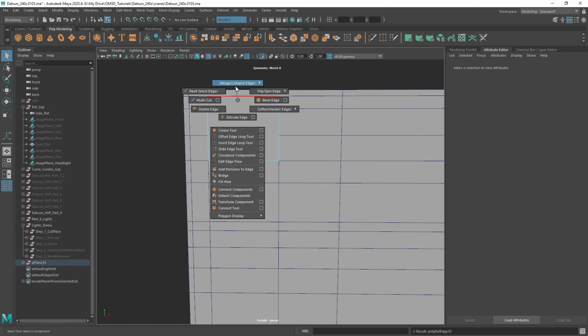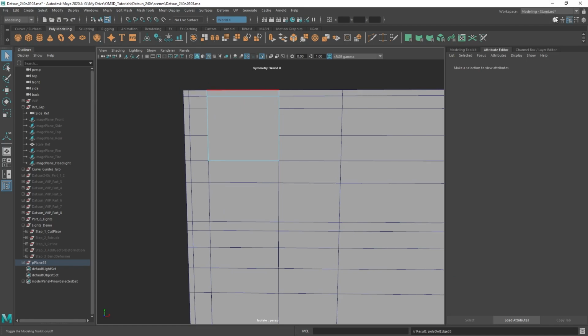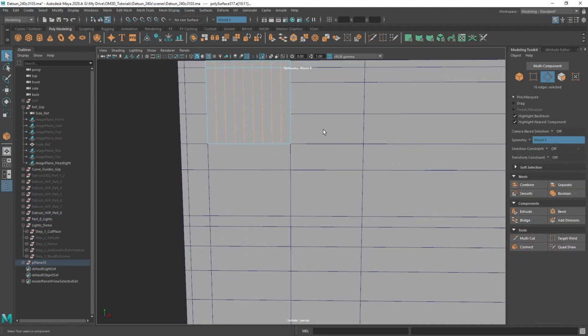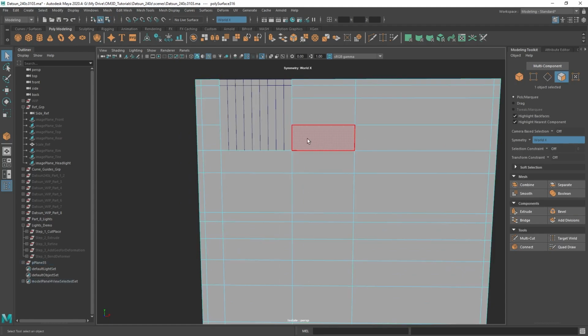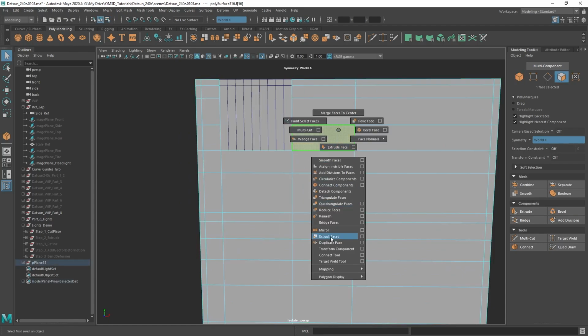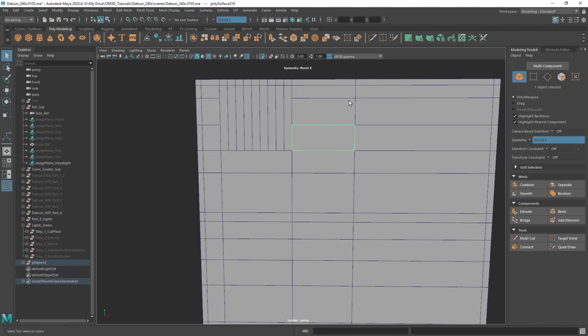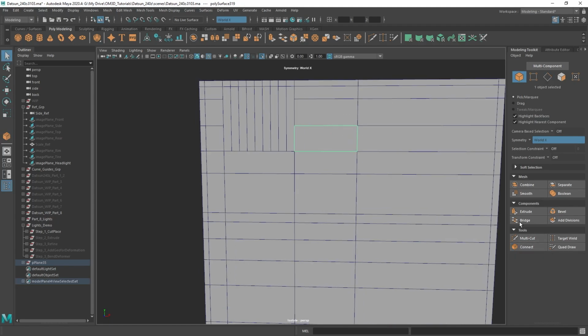And then I can go ahead now and use the connect tool. So I grab these and then I grab connect, and you can middle mouse drag like so, and you can add these throughout. And you can see that this works really well. So it is a bit of a tedious process, but it's going to give you the best results. So here you can see I can go ahead and connect and create larger panel pieces, right?